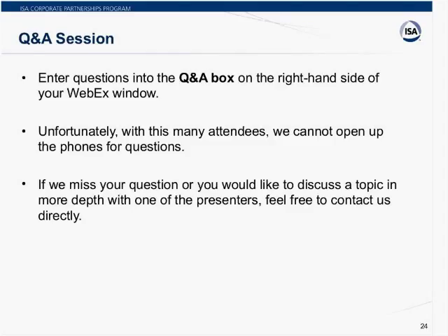All right. Thank you. Our next question comes from Alexandre, and he says, in the company I work, we usually associate FEL phases with feasibility study, FEL 1, conceptual design, FEL 2, and basic design, FEL 3. After that, detailed design, implementation, and commissioning is altogether named implementation phase. Is that correct? And then he notes, I'm talking about how our greenfield projects are broken down. Charlie, can you answer that one?